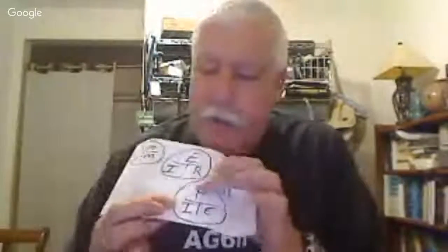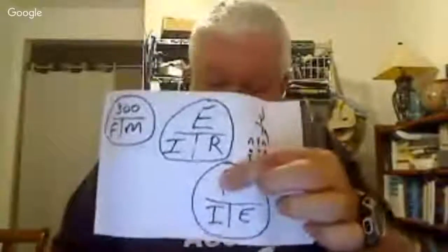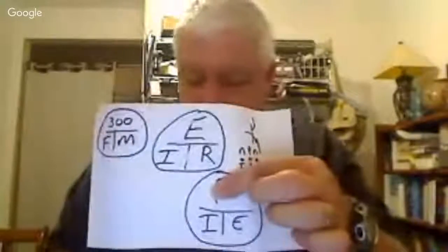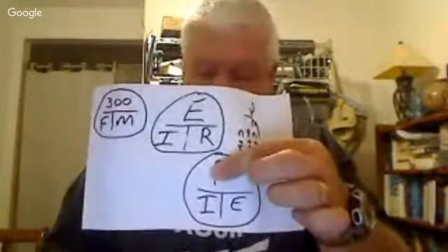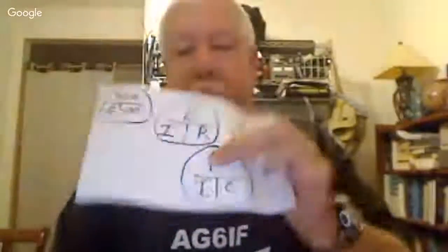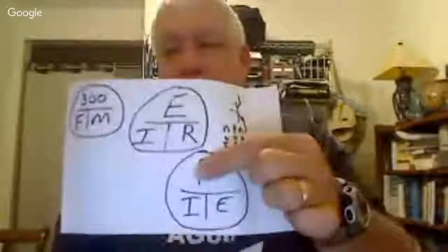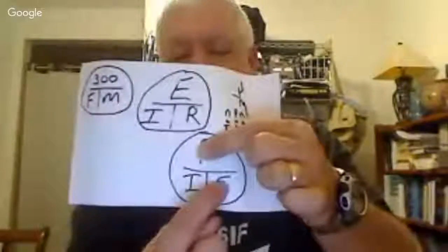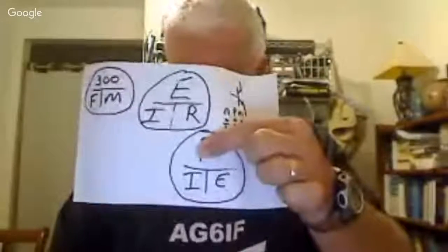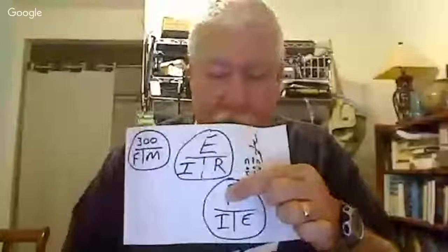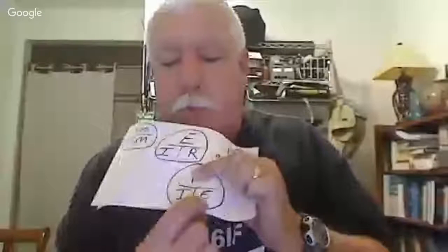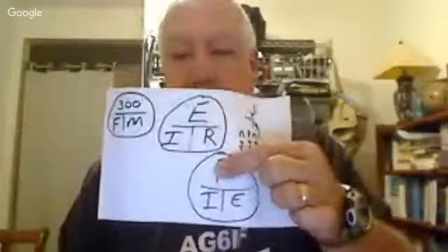They're asking for power, so I'm just going to cover the P. How much power is being used in a circuit when the applied voltage is 13.8 and the current is 10 amperes? So I is 10, and E is 13.8. We multiply 13.8 times 10. Simple, right? And the answer is 138 watts. I'm on question T5C09. They gave you the two values. You multiply them together, and there's your answer.